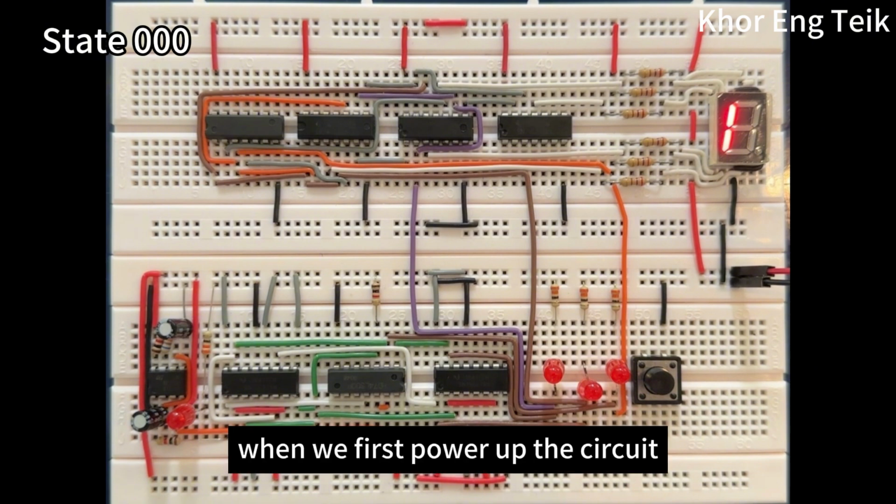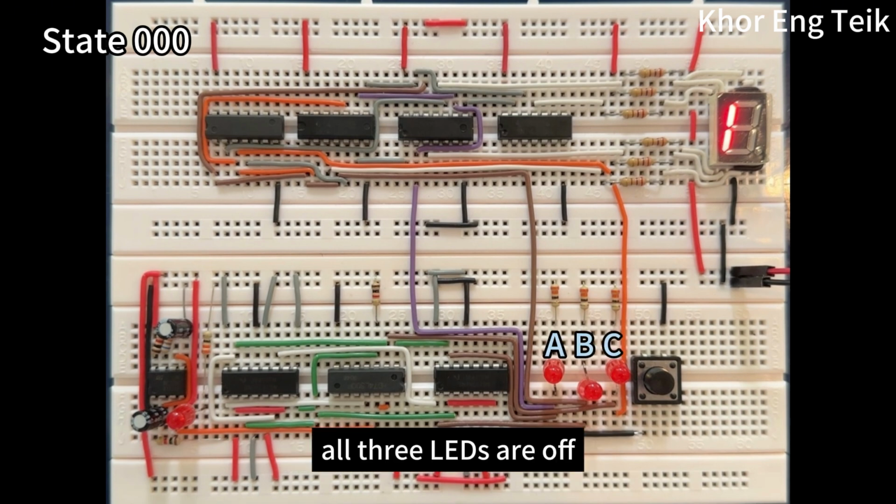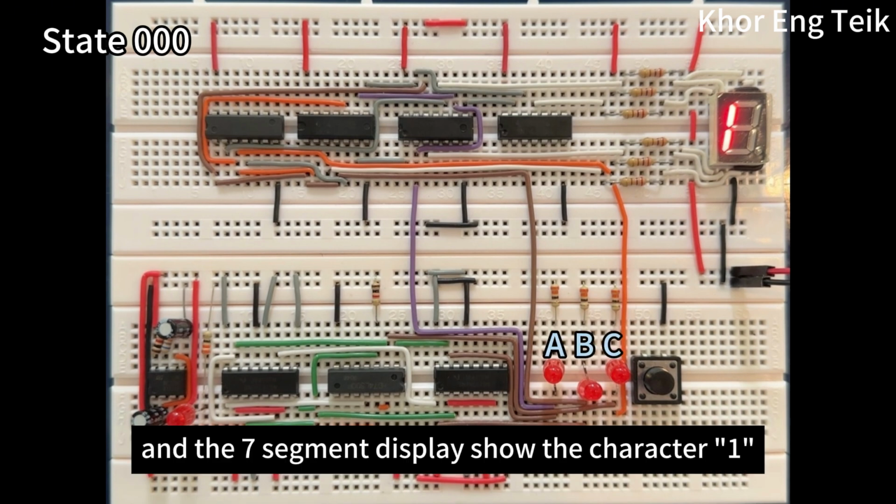When we first power up the circuit or when the reset button is pressed, all 3 flip-flops are cleared to 0. So the binary state is 0, 0, 0. All 3 LEDs are off, and the 7-segment display shows the character 1.